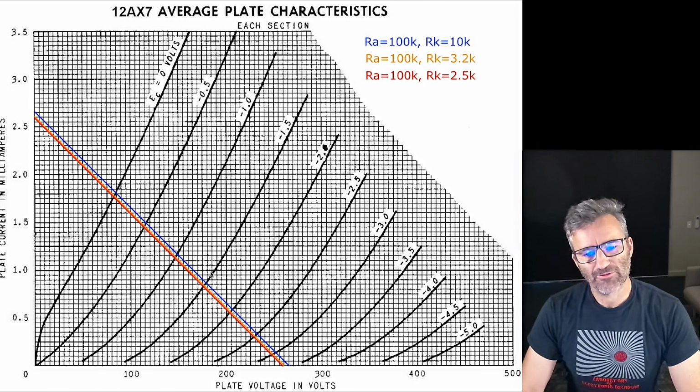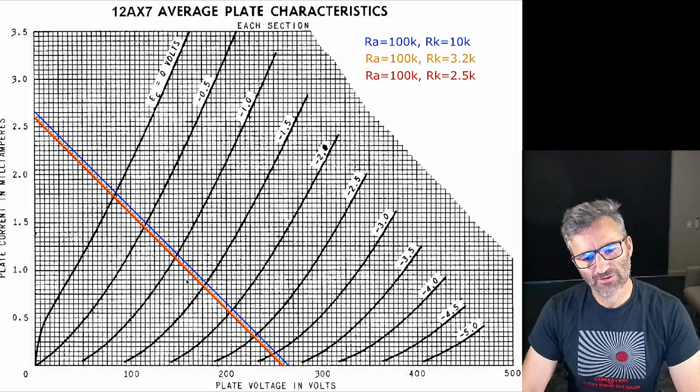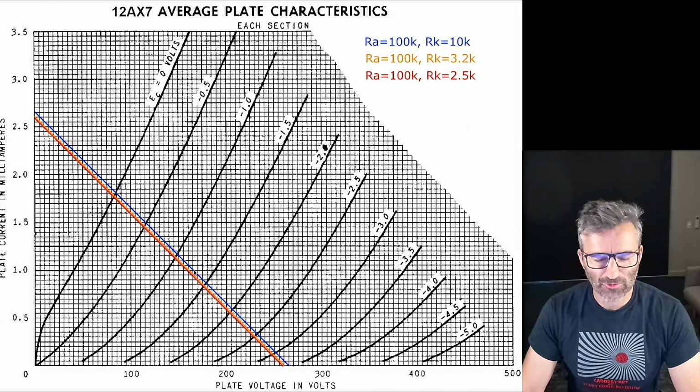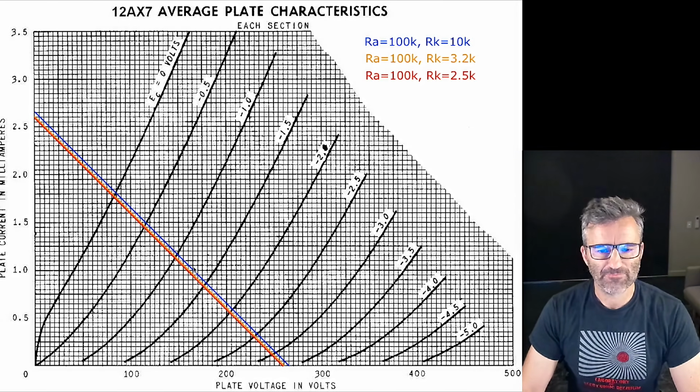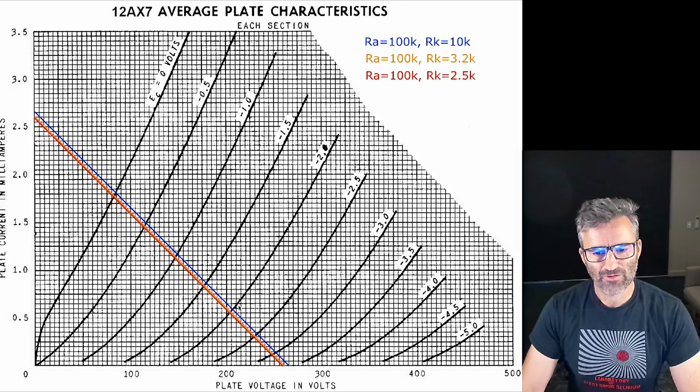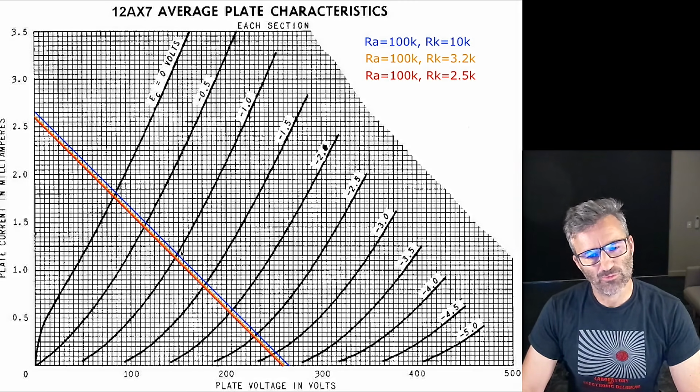So somewhere here in the middle is, let's call it the golden point, or the Goldilocks point, if you like, right in the middle. As you move an operating point or a bias point on the load line towards this side, you are going cold bias, and if you move from this midpoint towards this side, you're going warm bias.